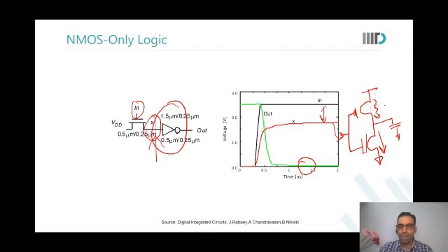Sir, how can we say that my NMOS is fully on, sir? You tell me. Sir, as my input is not touching the one position. When does NMOS enter into saturation region? Okay, VDS should be greater than VGS minus VT, sir. Is it greater than VGS minus VT?